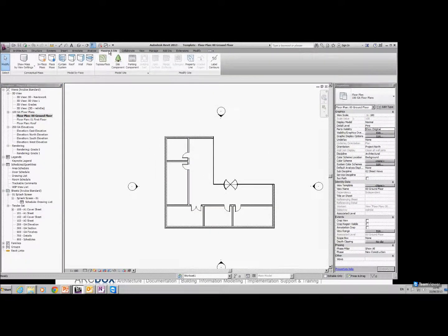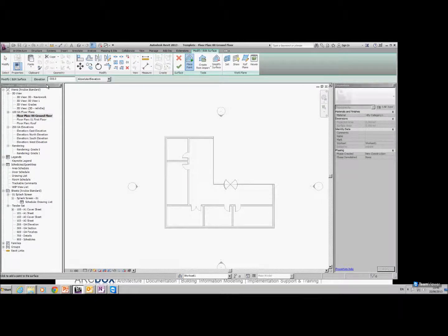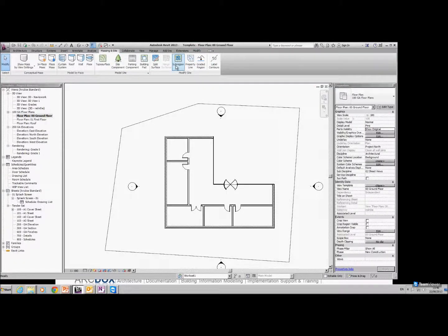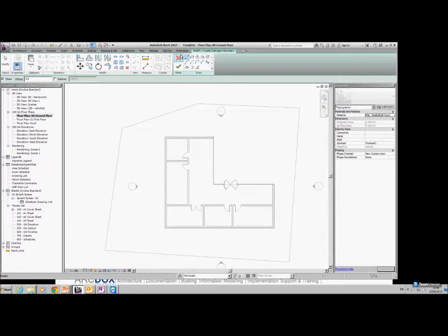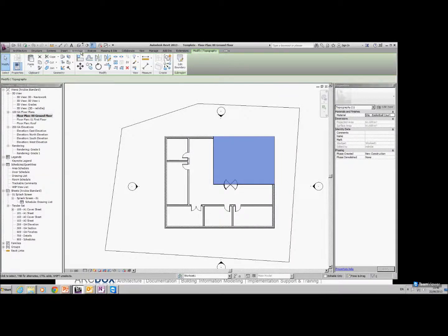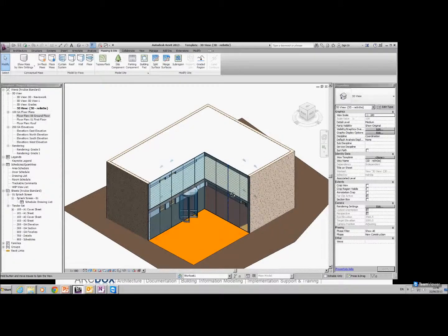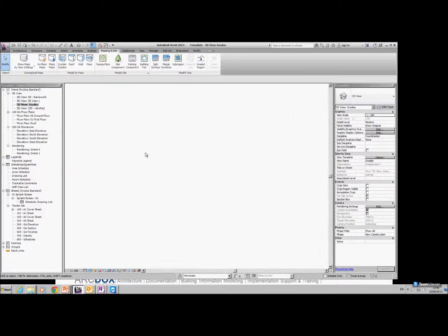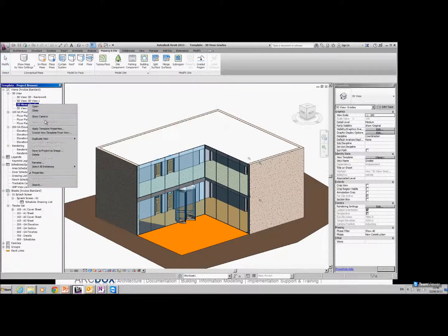I'm going to do one more thing just to make it jump out. A topo surface, just a quick little topo surface at 0. I want it all to be at 0. There we go. And also I want to finish that and then put a subregion. Finish that. Now look at that in 3D. Then we have a bit of development there. Go back into my grades and now I'll save this as grade 2.